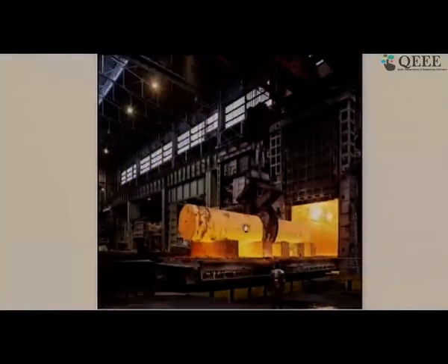The heating of this, and then while working it, it is hot, so you have very significant radiation also, but also a lot of convection heat transfer is taking place from it. There is no air being blown as such, but this piece, when it is moving, is causing relative motion between the material and the air, and that will cause convection heat transfer to take place.